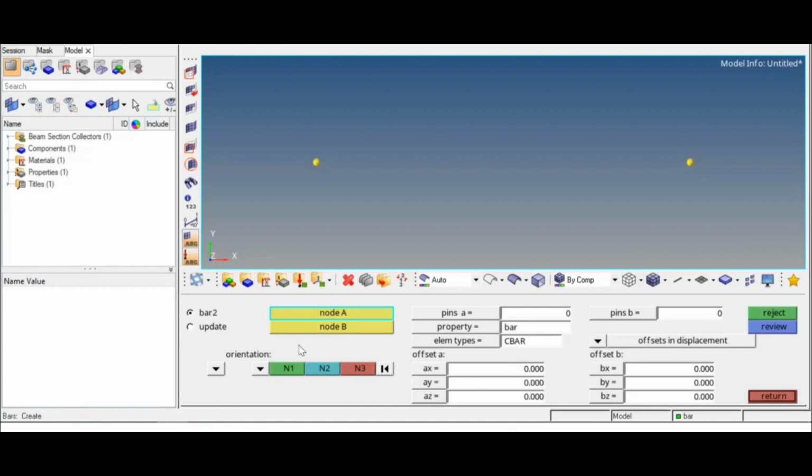So orientation is how you want to align the cross section. Take an example here. Let's say you have a water bottle and the length of the bottle is the length of the element. Now if you want to align the cross section, in this case the cross section is the cap, which is a circular cap. So if you want to apply that cap onto that bottle, you have to orient the cap in a particular direction, that is perpendicular to the x-axis in which there is the length. Then only you will be able to apply the cap, or in other words, then only you will be able to apply the cross section.